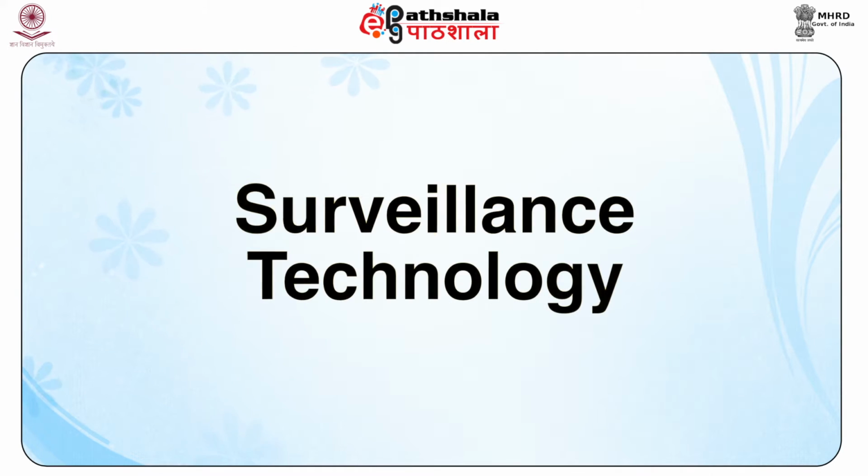Then we will talk about surveillance technology. There are 4 types of surveillance technology to be considered. First is analog and time-lapse VCR based systems. Time-lapse VCRs used for CCTV are different from the domestic machines, as firstly, a CCTV VCR is an industrial machine which is built to a standard that will allow it to run 24 hours a day. Secondly, VCRs used in CCTV systems are typically time-lapse machines that have the function of stepping down or up the speed of the recording tape at slow rates.